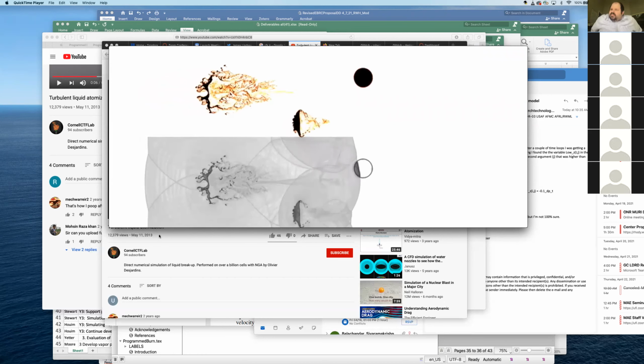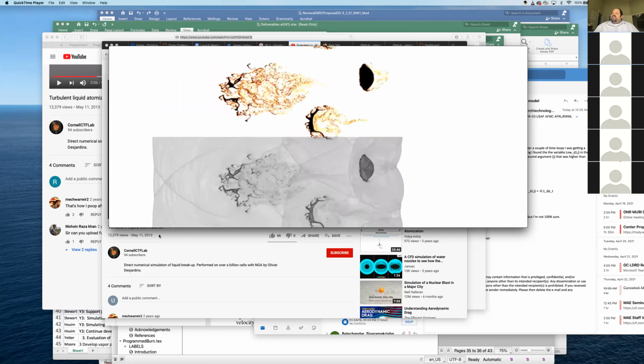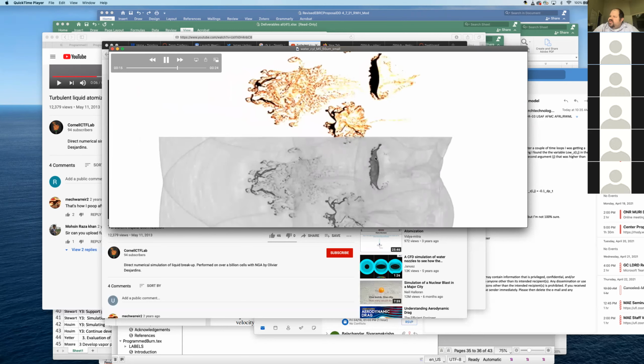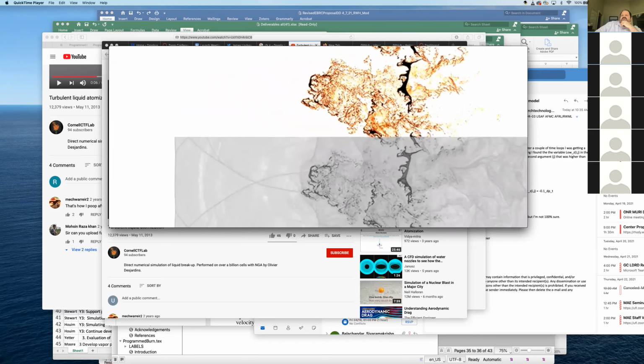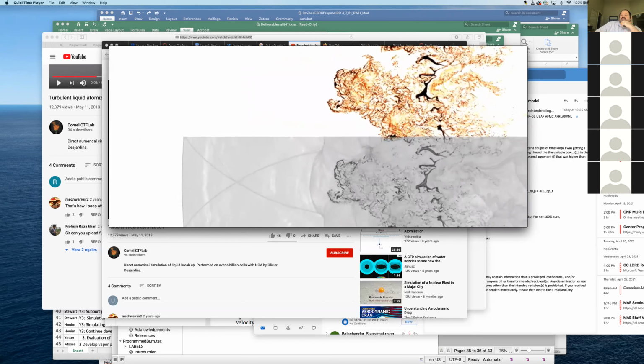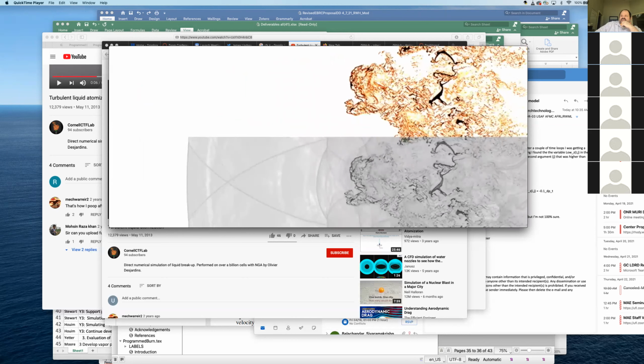And so this is a THINC approach, is that if you were to zoom in on the interface here of the gas-liquid, I don't remember what it is for this computation, but it'd be spread over probably about three grid points. So are there any questions with that? Okay, and I'll show some more. This is a diffuse interface method. Let's see, gotta find that.